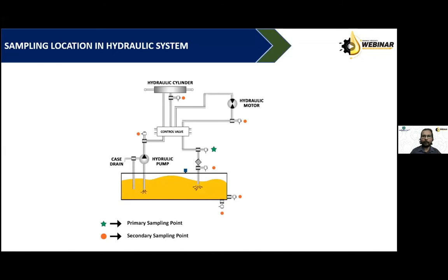And above the oil surface in the tank, we have some empty space called header space for the oil. It contains air. So whenever oil level goes up, air will come out. Whenever oil level goes down, air will come in. We call it breathing of the tank. Tank exhales and inhales the air.